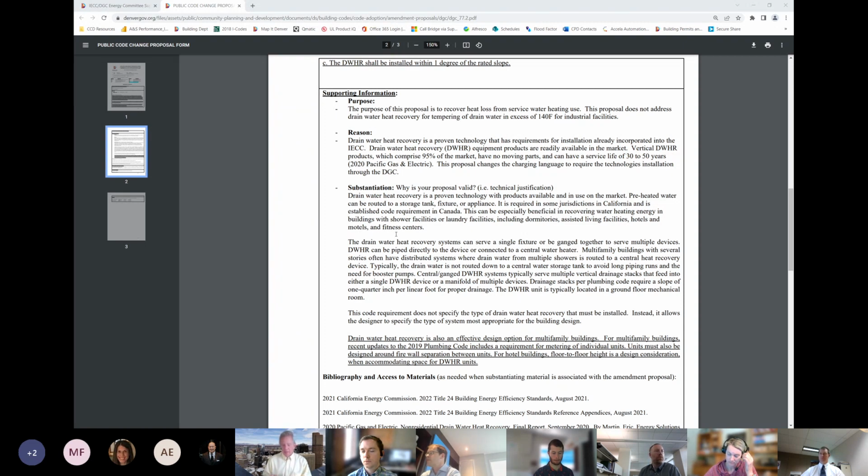The other item I would say, even within the green code, the only way these things really make sense is if you're not having to add a whole lot more piping to the system. Where these things make sense is in particular showers. Showers are wonderful because a shower already has a cold inlet and a hot inlet. And what you do is you take the regular domestic hot water to the hot inlet and you run the cold water through the looped pipe around the drain and then into the cold inlet, so that you don't need as much hot water because the cold water's doing the work.